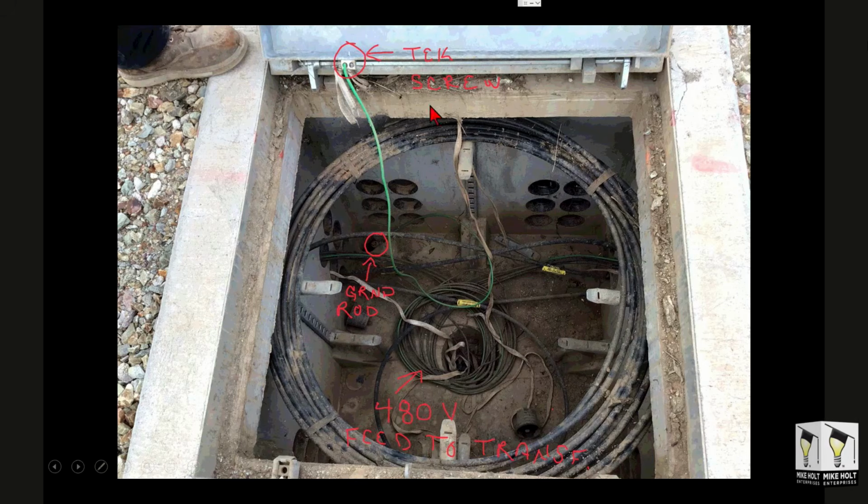You know what? This cover would have probably never gotten energized. But now you take a wire and connect it to the cover, and string it along among all these other conductors, thinking that you're grounding it to a ground rod. Now what would happen if the phase conductors somehow faulted to that ground wire?